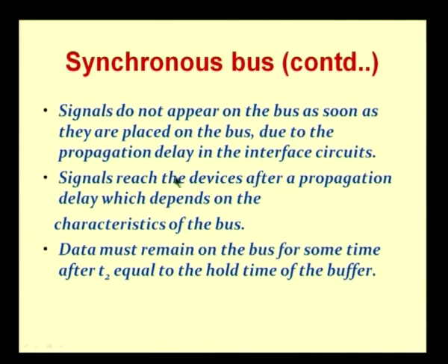Now, the next point that we need to remember is what I told you about the hold time. Okay. So remember that signals do not appear on the bus as soon as they are placed on the bus, due to the propagation delay in the interface circuits. Second, signals reach the devices after a propagation delay, which depends on the characteristics of the bus. Remember, there are two different propagation delays we are talking about here. One is the delay it takes for the signal to go on the bus itself, and the second is the delay in the interface circuits of the input output device that you are talking about. So before it can be placed on the bus, again there will be some delay. Okay. So both these delays have to be taken into account.